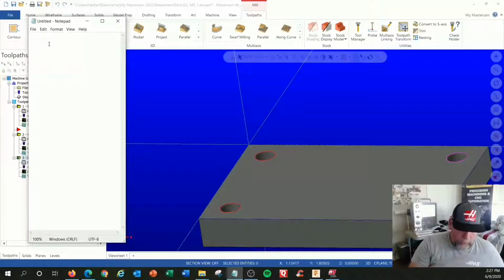So you've got to put a percent sign up here. And then you've got to give it a program number, the FANUC format program number. You get the letter O and, I don't know, 1, 2, 3, 4. I come from the 4-digit era, and now they're 5 digits. So you could literally just put 1, and it's going to be 00001.